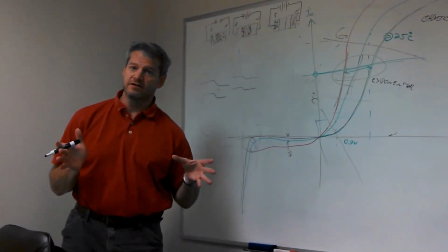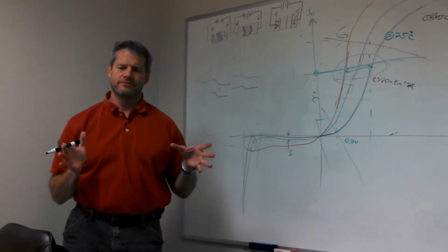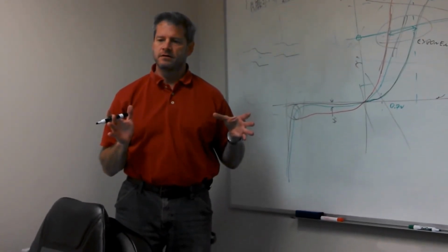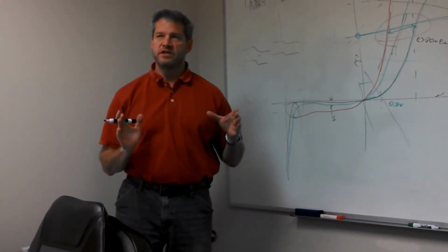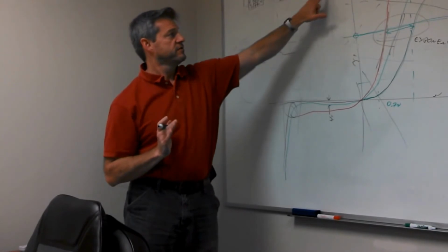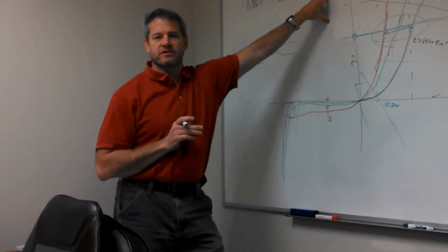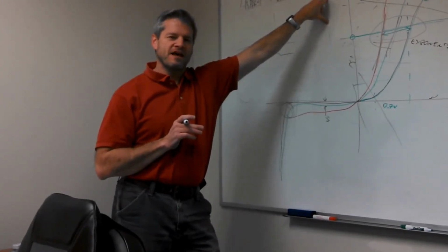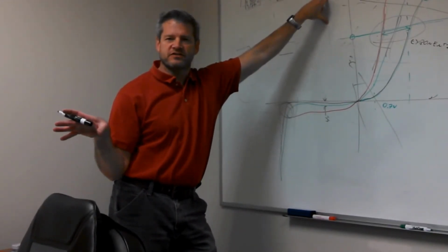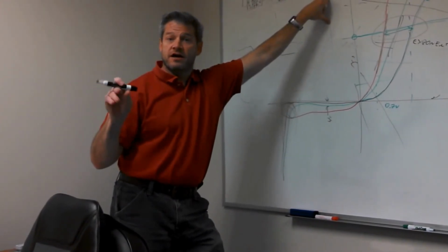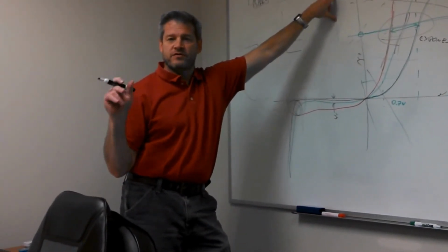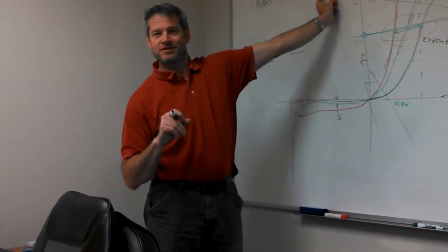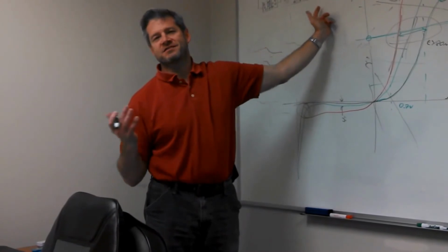There's a device called a varactor, which is a diode that is made, this is effectively a capacitor. And in a lot of our electronic circuits, like an FM tuner or TV tuner, the way they're doing the tuning is by changing a voltage, which changes the width of this, and you change the capacitance on the filters.